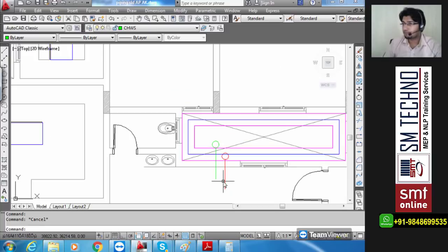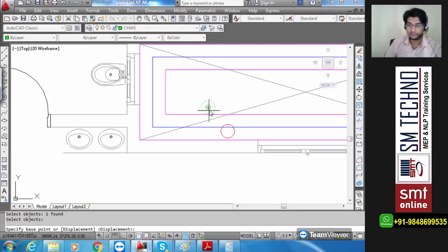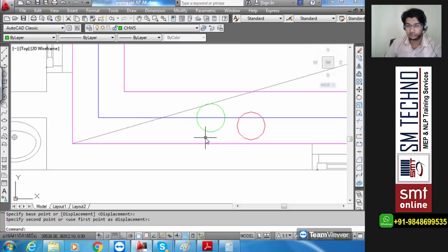Before you start doing the chill water pipe, you need to select it and delete. Otherwise also it will be deleted. You don't really need to do that. I can delete this one also. I only need the segments. It is not necessary that the return connection be below or the supply connection be above. They can be in the same level as well. Like this.